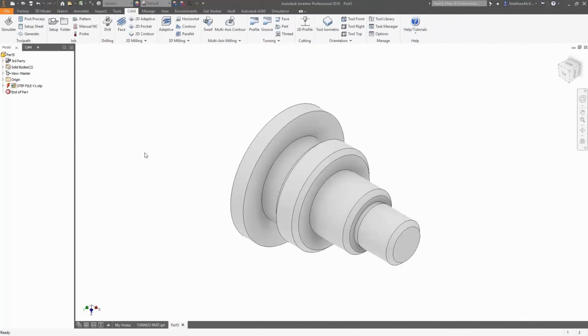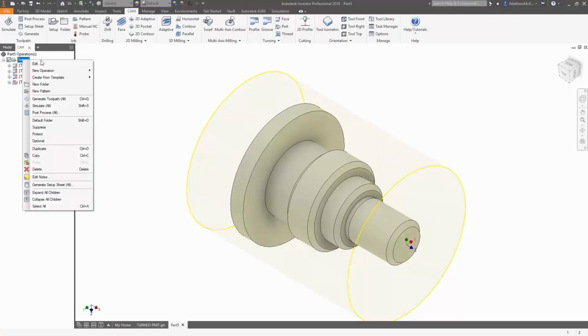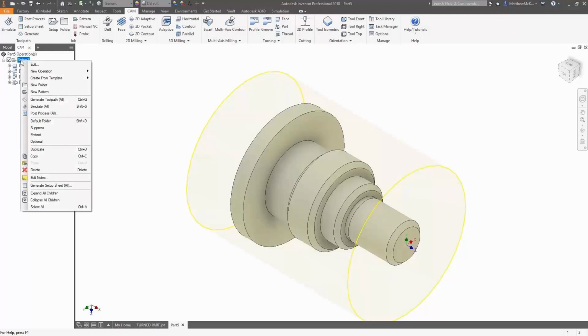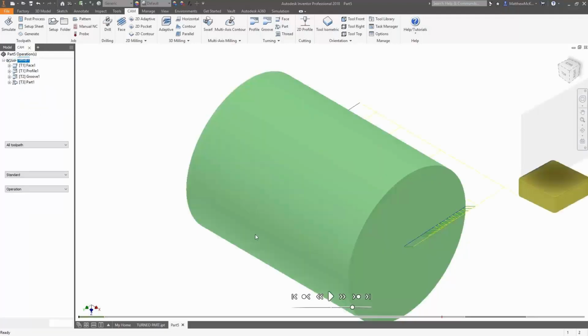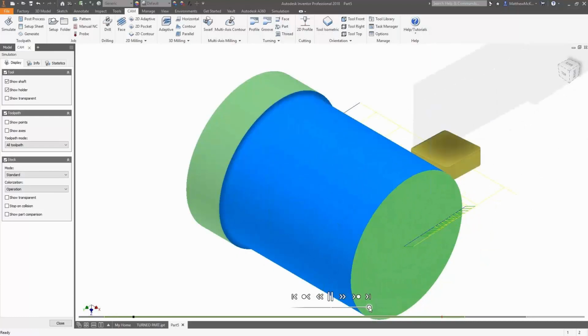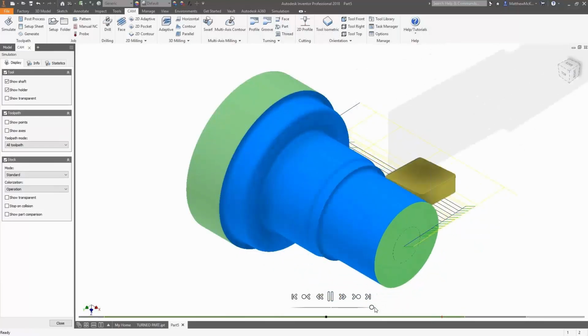So if we overwrite or replace the file, or we simply change it, you'll notice here we get the little lightning bolts to say that we need to update the design. In updating it, you will have noticed that there were a number of changes to the look, the appearance, and the function of the part. We can simply go back into our CAM environment, regenerate the toolpath, re-simulate to make sure that we're successful, and you can see here that we have a whole new part based on all of the changes that link through to that original step file.